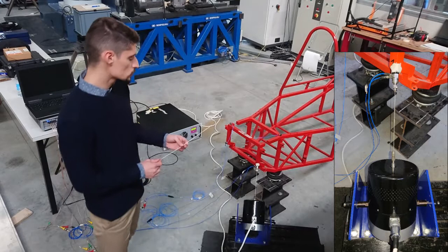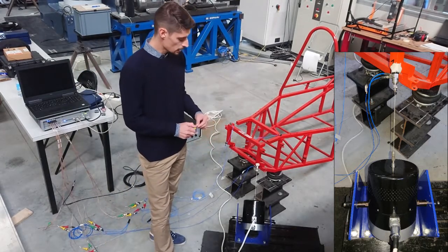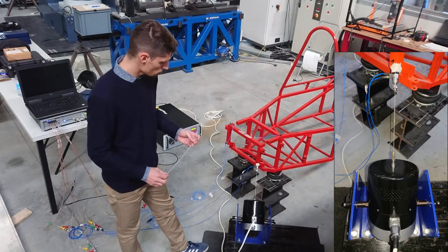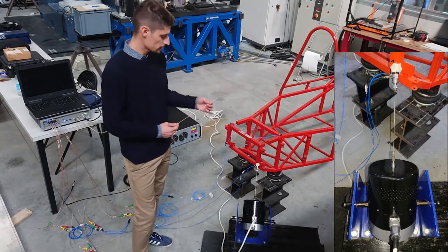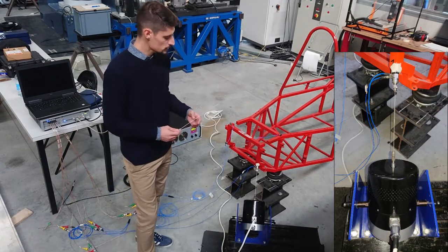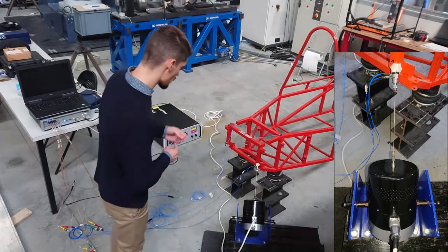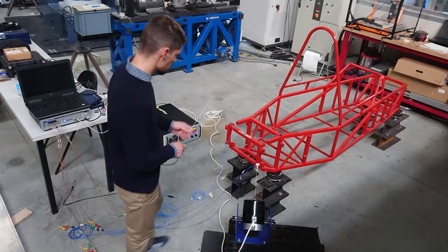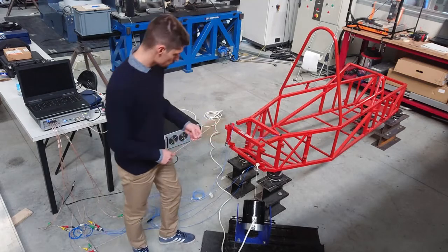An easy way to determine the right position of the stinger and the correct length of your stinger is to make several runs by varying the length of the stinger, and try to observe the change in the measurement. Okay, we already spoke about the structure, the shaker, the stinger.